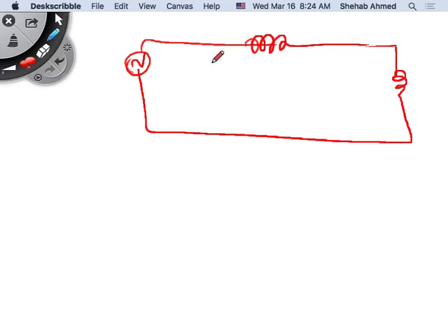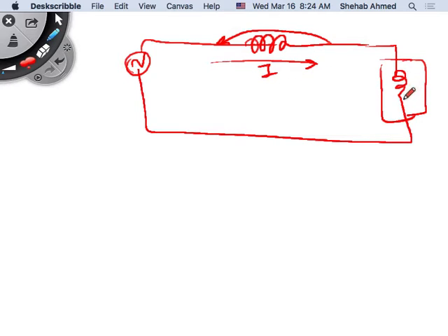Current was flowing through this system. This is my load in this case, for example, and then there's a voltage drop due to this line's reactance, because current here needs to go supply this inductor. This inductor is actually consuming only reactive power, right? So this current is only reactive in this case. So what I'm doing now is putting a capacitor right across this load. So what is this doing?